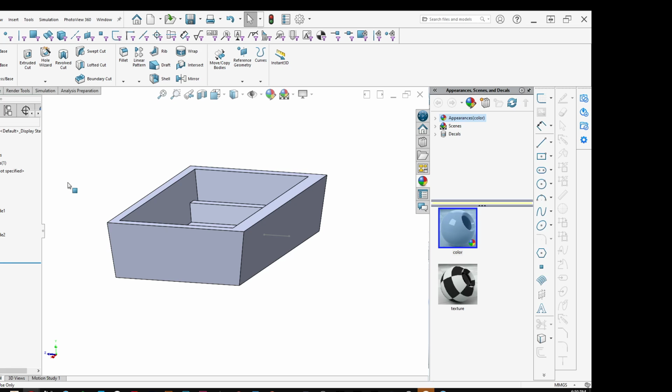But really, a large part of material thickness comes down to how strong does this need to be, along with how many ribs do you need, how much thickness. If I am designing a cup that I am drinking out of, I don't need to have it all that strong. I don't want it to be a solo cup, because I want more rigidity than that. But I'm not going to stand on the cup, so I don't need as much plastic as that. And you have to determine what that is going to be.